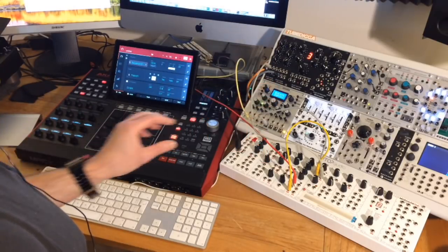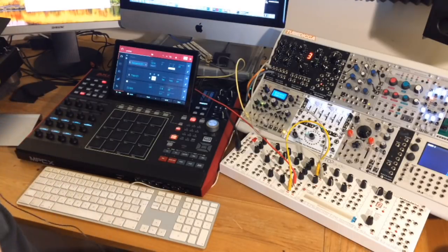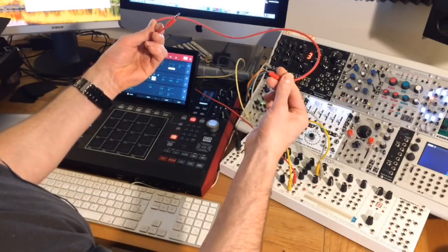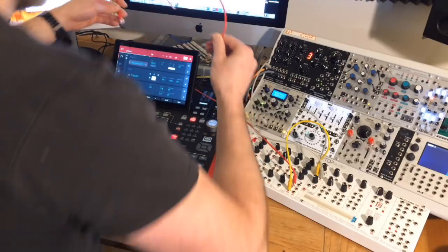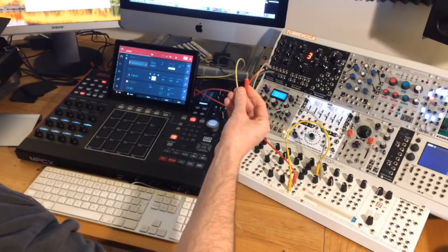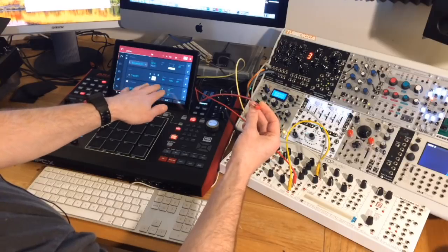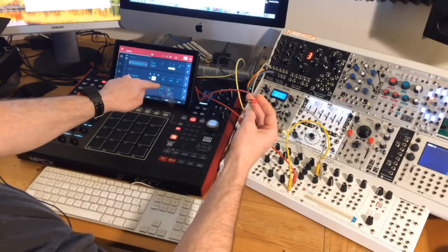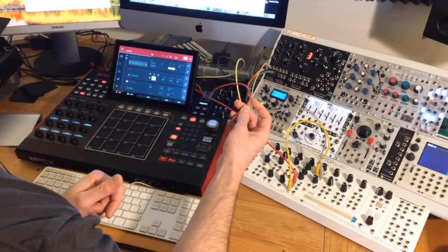modular synthesizer. We can use our Q-Links. So let's take another cable. Again, I've got this long red cable. I'm going to take that out of CV port 6. So that's now coming out of CV port 6. As I said, you can't configure that additional port to do anything from here. We've just got the CV port and gate, which again are most commonly going to be used for pitch and